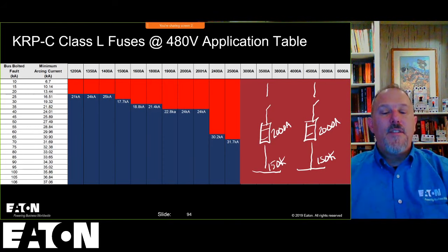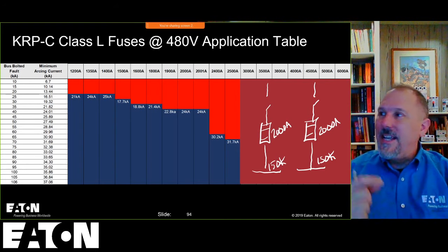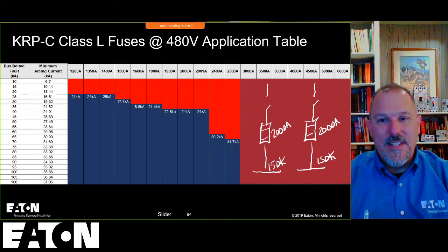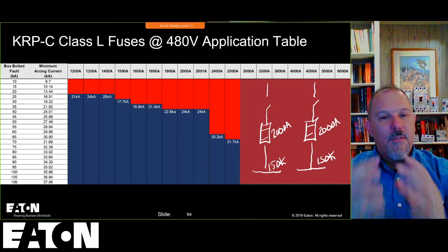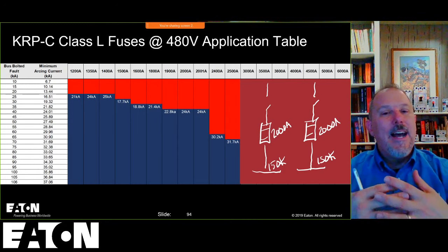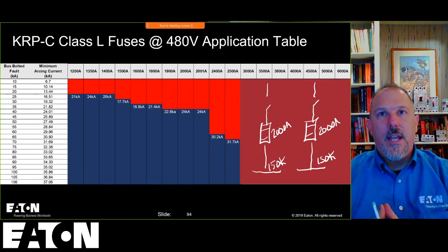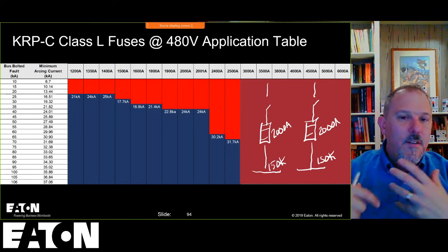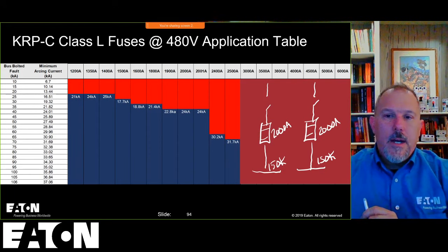Now I have 150,000 amps on a 2,000 amp switch, which I know only takes 24,000 amps to get a clearing time of 0.07 seconds or faster. And now I don't need to provide a technology. I can provide this evidence to the AHJ. I don't need to do anything with regard to 240.67. So that is an important aspect of how to deal with this section in the code.